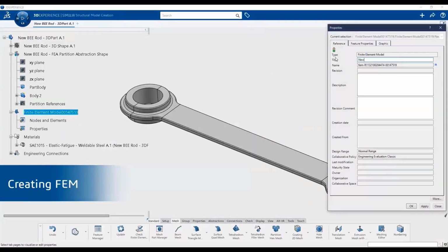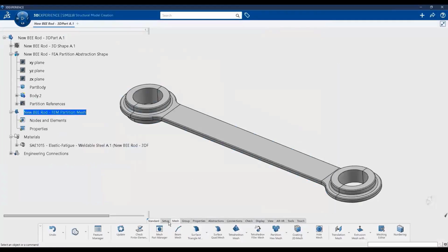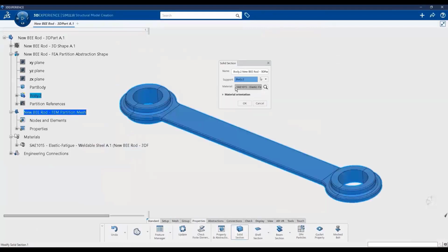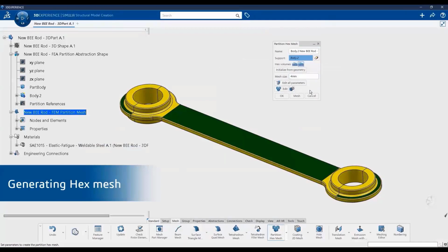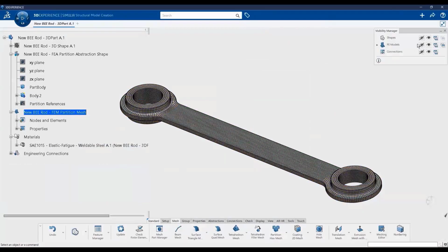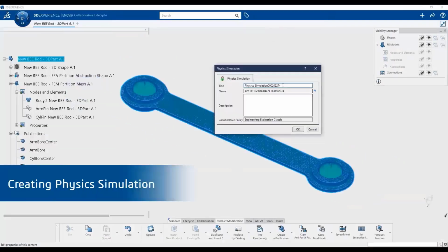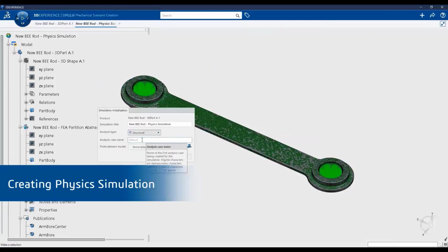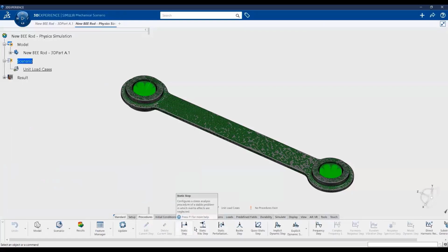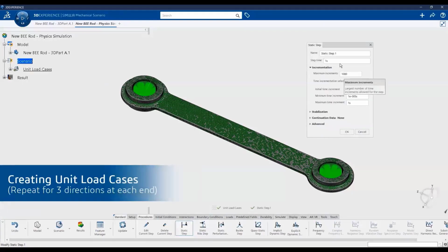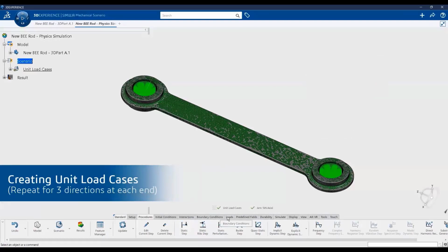So again, we are creating a mesh for this specific part. And here you will see we're applying what we call an X mesh. This is an advanced mesh. We can generate this type of mesh with, let's say, some cubes. This type of mesh, for example, we cannot do in SolidWorks Simulation. We need advanced simulation tools or simulation capabilities to do this type of mesh. And we do have this type of mesh now with all the technology we have on the 3DEXPERIENCE platform.